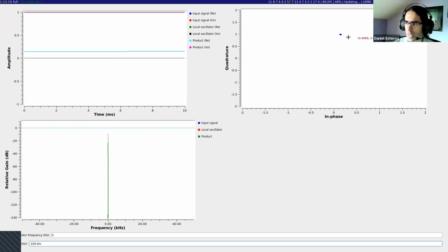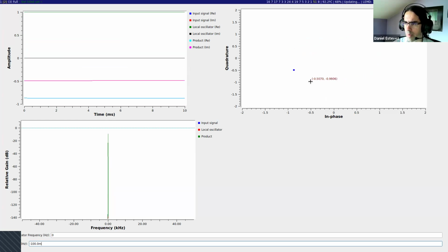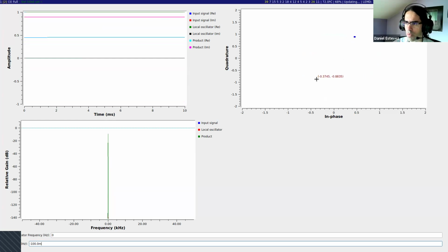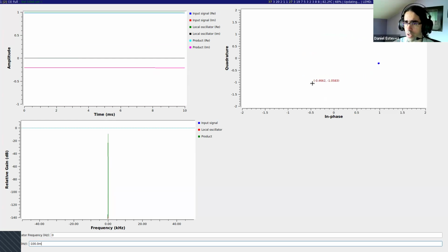So if we look at the complex signal as a whole, we can plot it on the complex plane and figure out whether the frequency is positive or negative by looking at whether it is rotating clockwise or counterclockwise. Because we have two dimensions, it makes sense to speak about this thing rotating clockwise or counterclockwise. Think of a wheel.